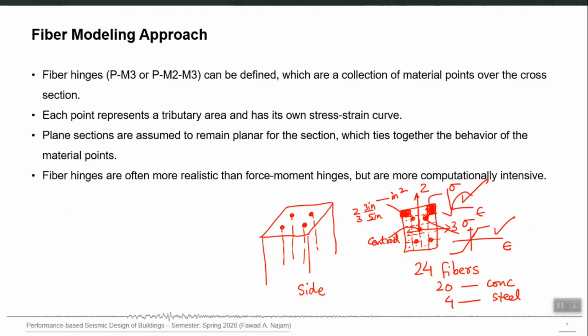But additionally, when you use that approach, you can even go to each fiber's results also. Like I have given this particular fiber, let's say, this stress strain curve I have defined in the program, and on that I will also define IO, LS and CP, because now our action deformation curve is no more moment rotation, it is stress strain.